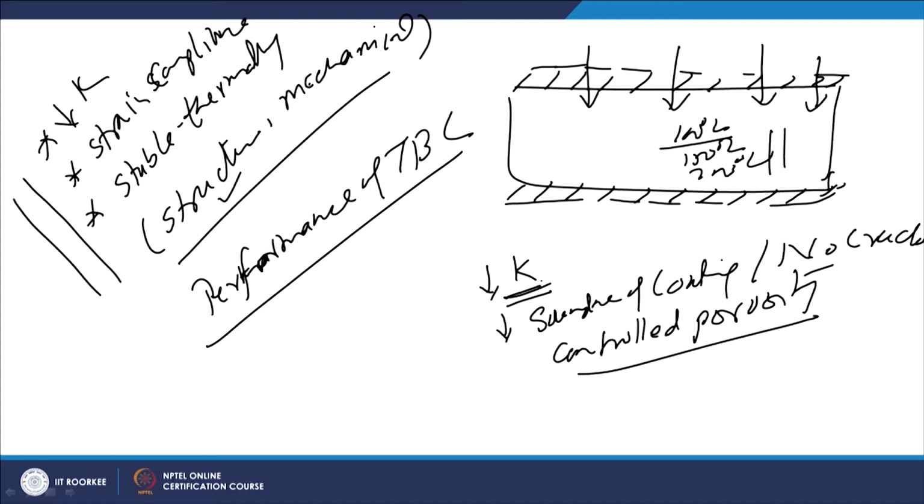These are made of lower thermal conductivity material, so the transfer of heat from the outside to the main component can be reduced. But if there are cracks which are through, then heat will be able to easily transfer to the main component.